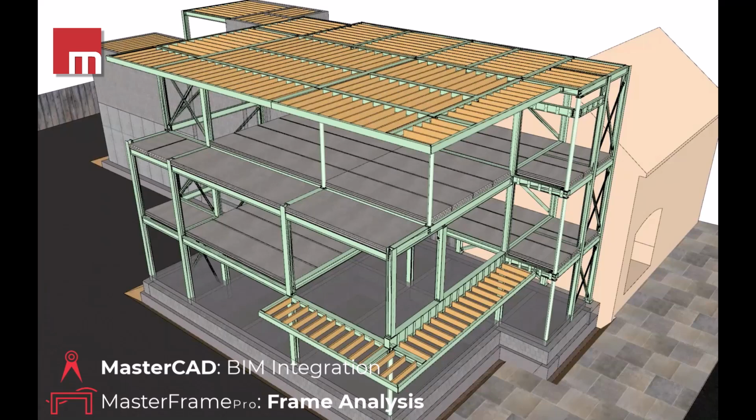This building was fairly straightforward, but for more complex arrangements, a popular option is to import a CAD drawing as an overlay in MasterFrame to use for maximum accuracy. So in MasterFrame, the model was then linked to Revit using the MasterCAD BIM Integration module, which allowed for the development of the final CAD drawings. We're always interested to hear how people use the MasterCAD BIM Integration, so if you've any experiences you think are worth sharing, just let us know in the chat box.